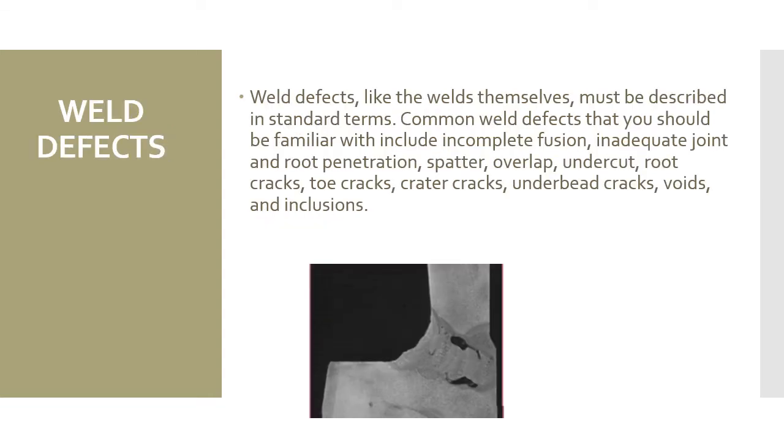Weld defects. Weld defects, like the welds themselves, must be described in standard terms. Common weld defects that you should be familiar with include incomplete fusion, inadequate joint and root penetration, spatter, overlap, undercut, root cracks, toe cracks, crater cracks, underbead cracks, voids, and inclusions.